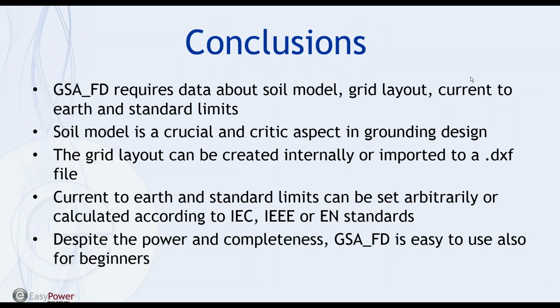This webinar is related to the module GSA FD of the software XGSLab, the most accurate tool in the market for grounding calculations, because it is the only software specialized in grounding design, able to consider a multi-layer soil model, frequency dependence of soil parameters, both self and mutual impedances, propagation effects, and the most used international standards, IEC, IEEE, and EN. We have analyzed step by step how to perform a grid analysis, a grid design.